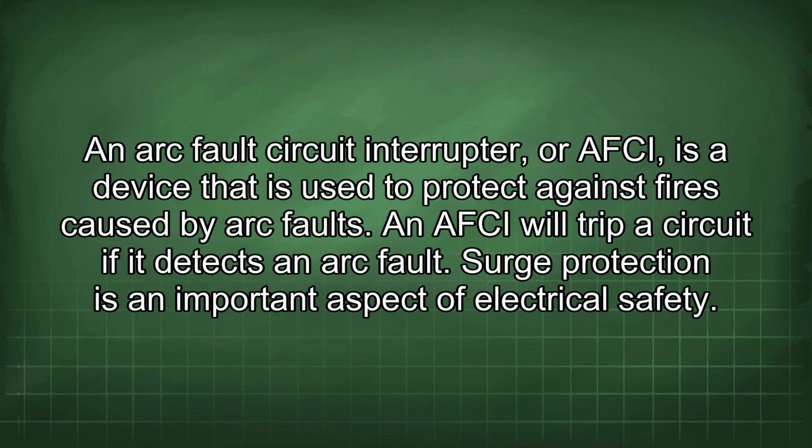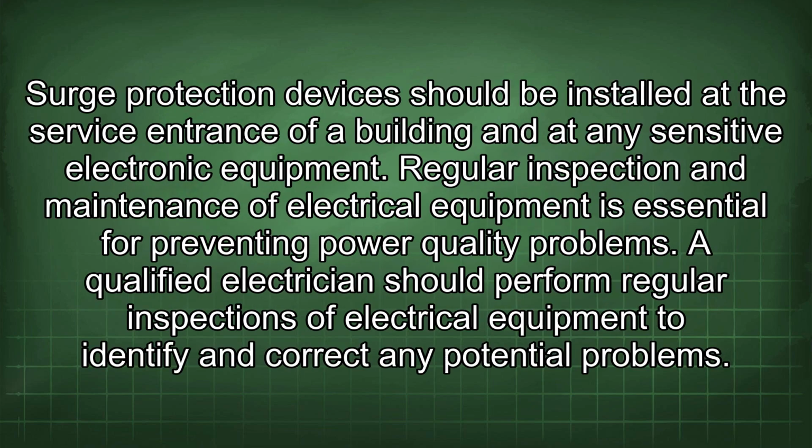Surge protection is an important aspect of electrical safety. Surge protection devices should be installed at the service entrance of a building and at any sensitive electronic equipment. Regular inspection and maintenance of electrical equipment is essential for preventing power quality problems. A qualified electrician should perform regular inspections of electrical equipment to identify and correct any potential problems.